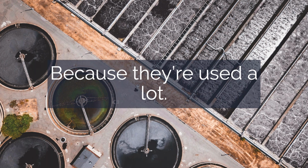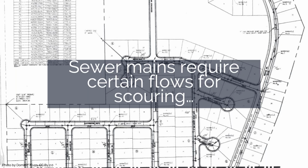And of course, in your day-to-day working life, if you're actually working as an operator right now, whether you're a trainee or you've been at it for a while, you will recognize that these are numbers that you have to have some facility with, things that you have to understand. For example, as we talked about in an earlier session on collection systems, collection systems are designed with certain flow ranges in mind, so that, for example, they can maintain their minimum scouring velocity during average or peak flows and don't get backed up.